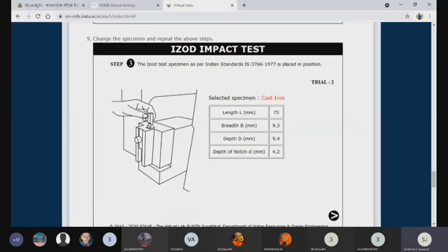Depending upon all these criteria, we make the sample weak by removing the 2 mm. Once you remove the 2 mm from the sample with the help of the hacksaw blade, it becomes 8 mm, because from here 2 mm is groove, means 2 mm is already gone. How much is the rest? Yes, 8. Now you can take the effective thickness or effective area. Effective thickness will be 8 mm.